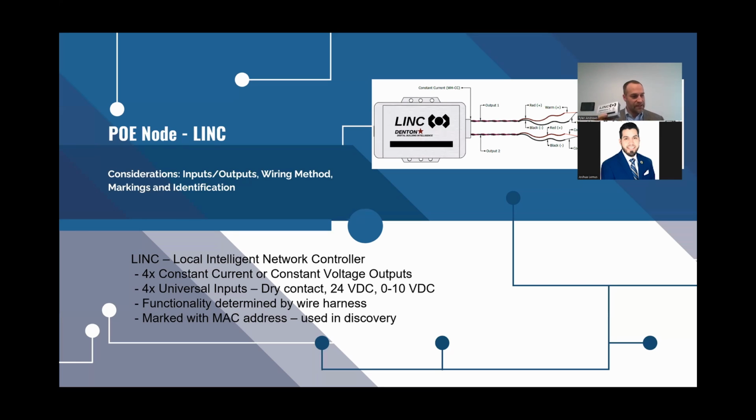The reason why we picked that is because we chose an off fixture node, so that you could pair this with a whole wide range of light fixtures. And that's a really important distinction, is you could tell your local code official, hey, I'm going to tear the AC driver out of this light fixture. And he goes, well, that voids that UL certificate. No, this is UL certified to replace AC drivers.